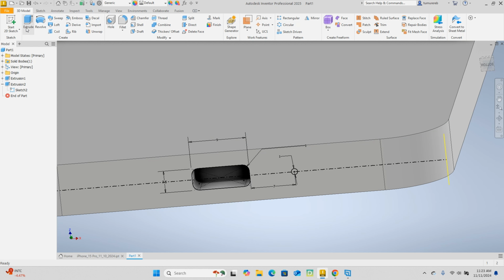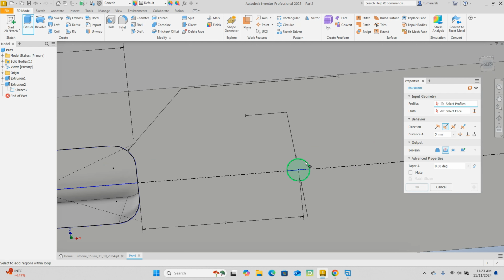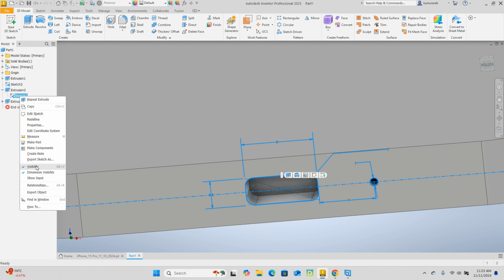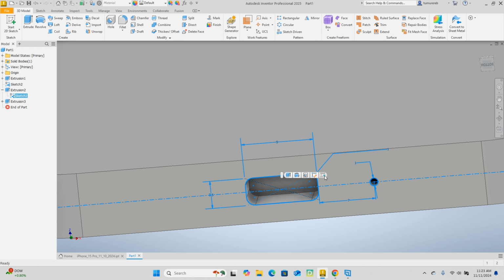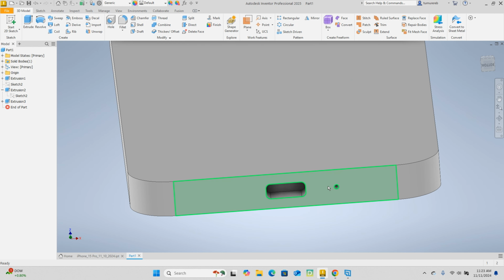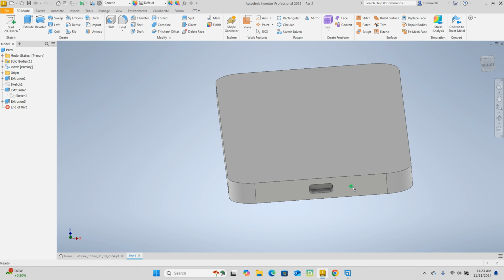Now we can extrude that circle as well. How much do you need extruded? Same distance we just did, 5. Let's go ahead and make our sketch invisible and check visibility, or click on this light, whichever. Okay, we are going to take advantage of rectangular pattern to just make a copy of this across.